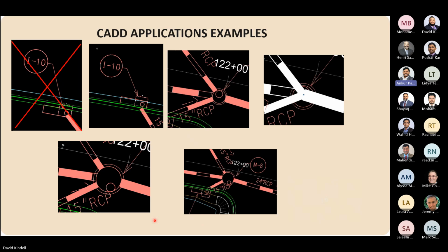Another easy thing to miss: when you're drawing them, snap to the center of the manhole, because that's actually how they're going to construct it. If you show it going into one corner or one side of it, they're not actually going to construct it that way. It may look like the manhole will fit, but when they go to construction, they'll call us and cause a headache. It's easy to do, because in review it's going to be tiny and we're not going to notice. So when you're drawing it, that's something that needs to be done correctly.